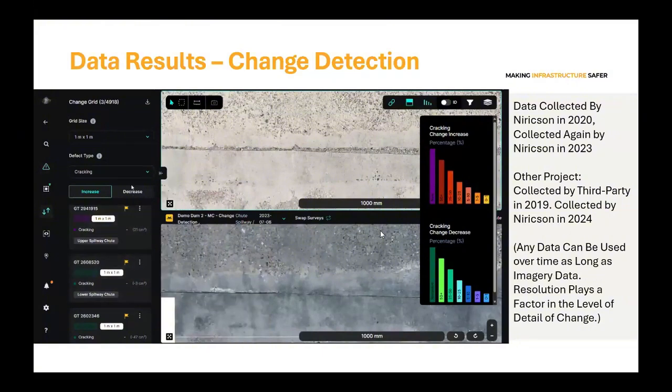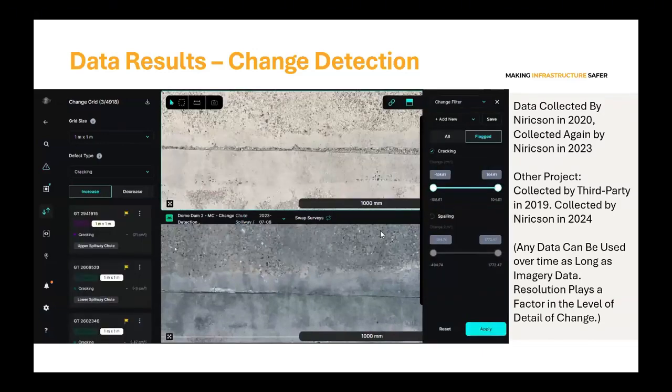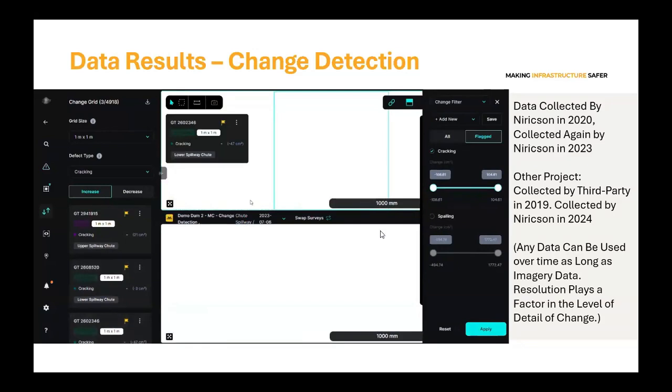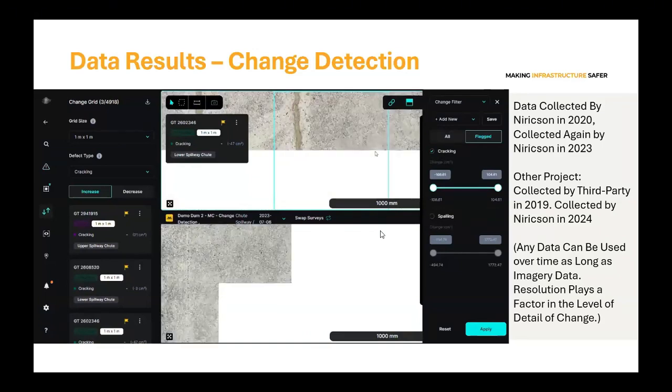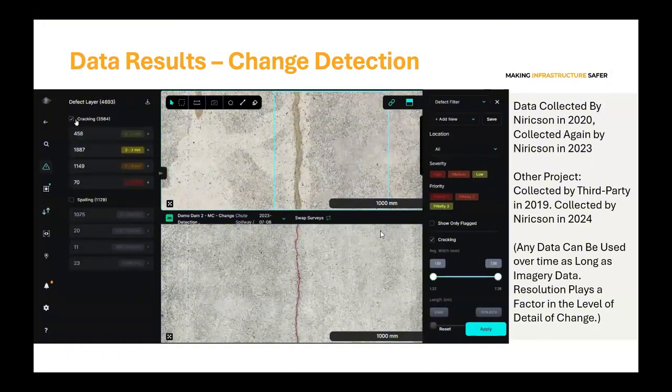It automatically lets us know how fast our structure is deteriorating, both on a 50,000-foot level, right? Which of my assets are deteriorating the fastest? And on a more granular level, you can zoom in and see where you need to prioritize your attention on specific assets. And you can see where that crack sealant's been applied and where it's working effectively and where it's not.